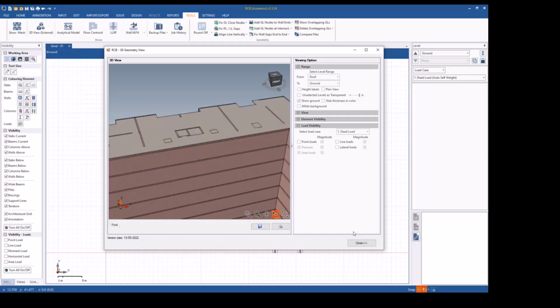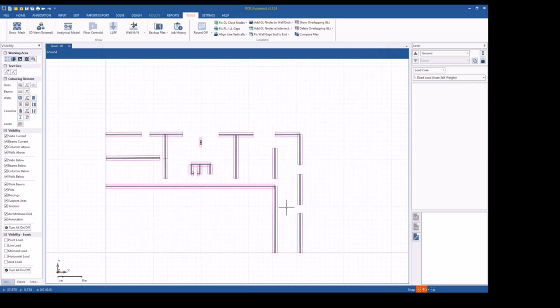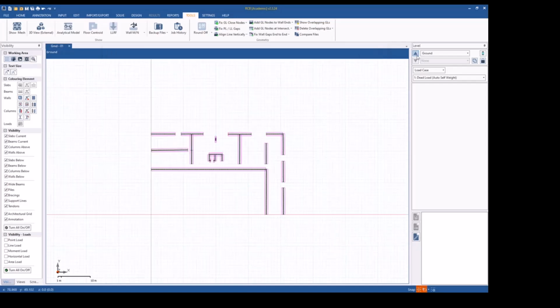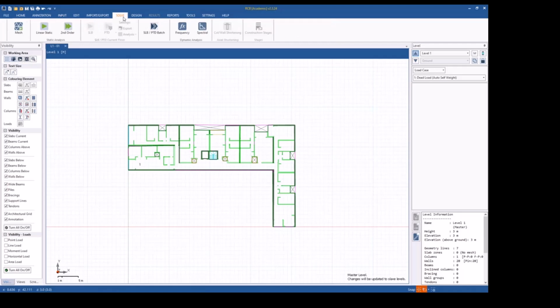We just want to define the thickness of the slab. As I said to you, this will be doable after we mesh the slab. So let's do it now. You can see it. And after that, I will put for you the loadings when we talk about the loadings. So it doesn't matter which level I'm going to go to mesh the slabs. You just go to solve and click on mesh. Now for your exercise, I think anything below 0.5 meter will be accurate enough.